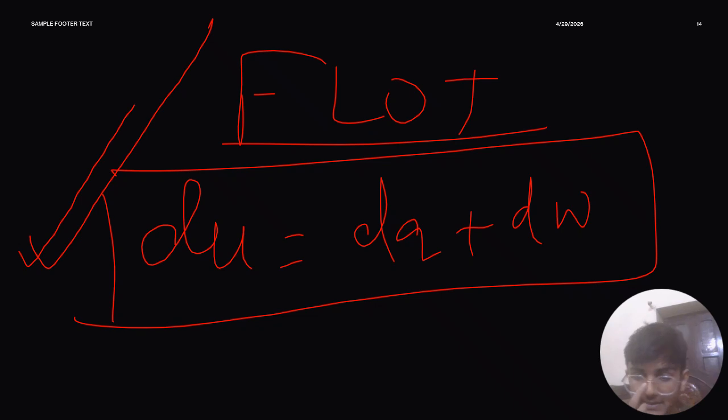We'll use it in different cases and apply it. First you have to just absorb this equation, that dU equals dQ plus dW. It is saying that if we are concerned with the work done, then the change in internal energy minus how much heat exchange there is, if we subtract these two quantities, we will get the net work done. We can verify it with the generalized formula of work done also, which I discussed earlier, that is the integral of PdV. We will use that also.